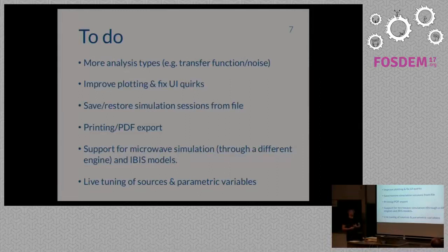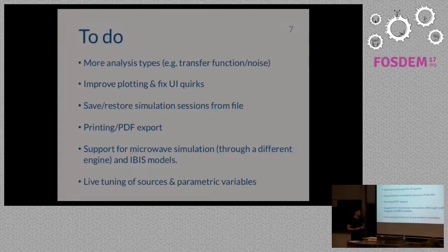One ambitious feature that we don't know if it will ever happen is support for microwave simulation, probably through another kernel like Qucsator, and support for IBIS models for signal integrity simulations. The last point is live tuning of sources and parametric variables, as we currently only support RCL components.